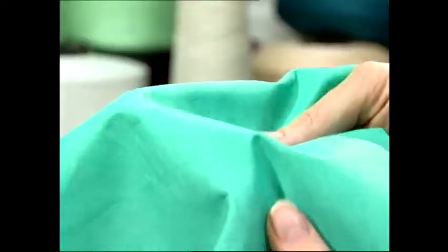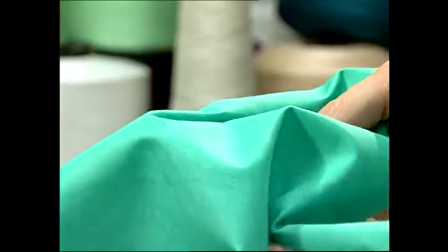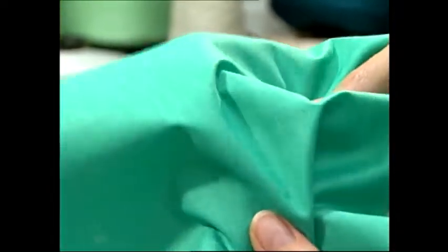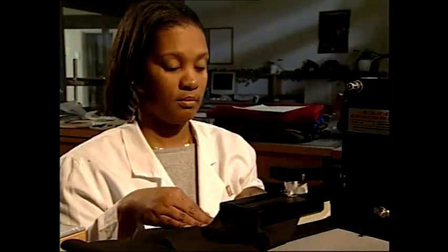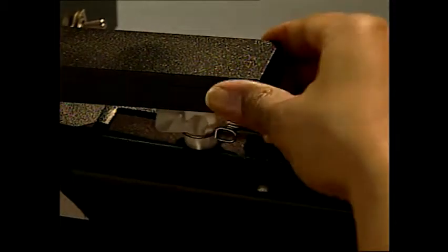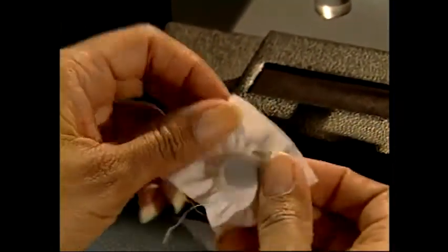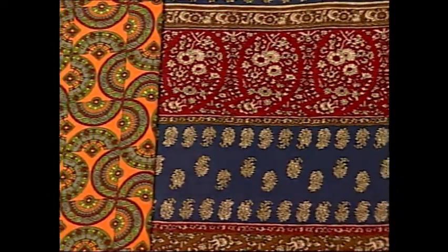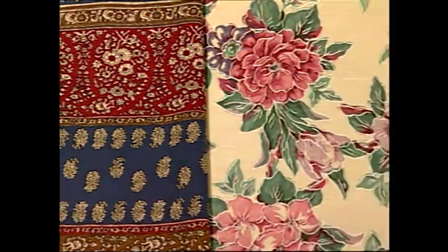Hand modifiers, most specifically softeners, are often incorporated with pigment print formulations. While these additives may improve certain aspects of the print, they may also interfere with the binder and should be used with caution. Some drawbacks of pigment prints include poor crock fastness, especially on deep shades, and stiffening of the fabric so that it takes on a rigid feel. Their wide shade range, as well as the flexibility and simplicity of processing, make pigments an extremely popular choice for both blended and 100% cotton fabrics.